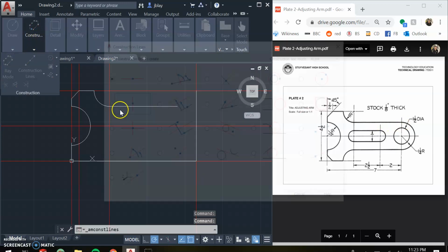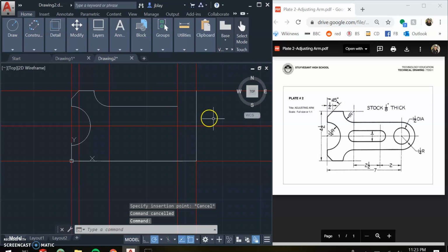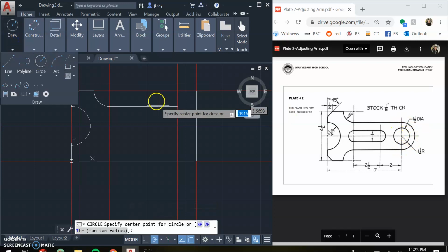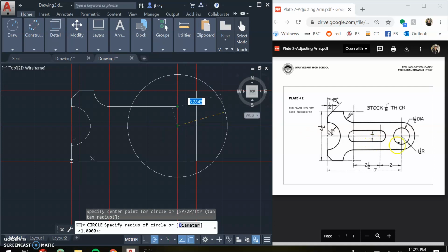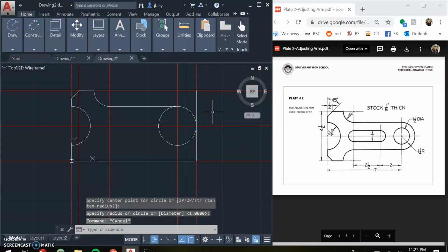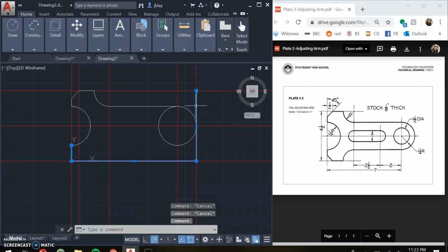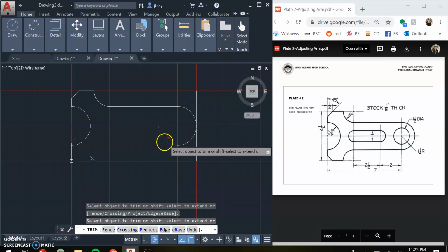So now I'll draw a vertical construction line that cuts through that point. And this will allow me to set up the arc that goes over here. If I've done everything correctly, this arc should be lined up where this point here will be exactly the same as this dimension here. So from here to here should be 1.25 inches. And it is. And it should be the same over here, 1.25 inches. And it is. I'm going to click. And then I'm going to trim everything down. I'm not going to delete this line out here just yet. So trim up this circle.